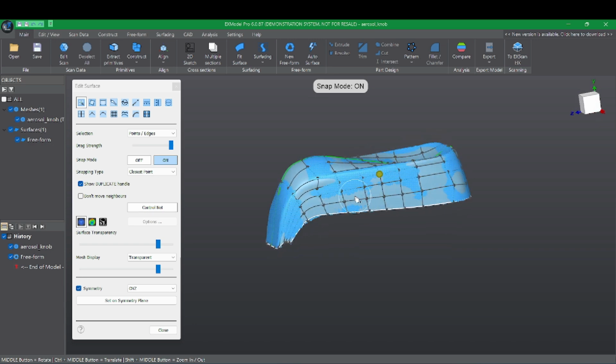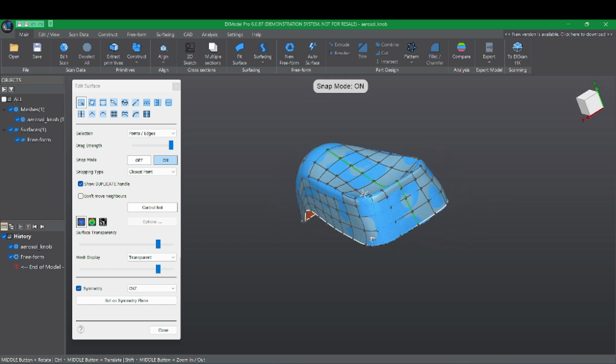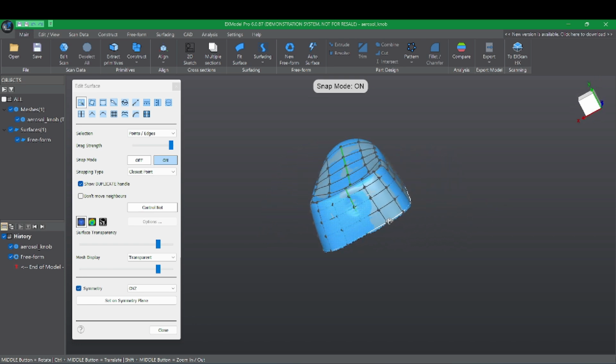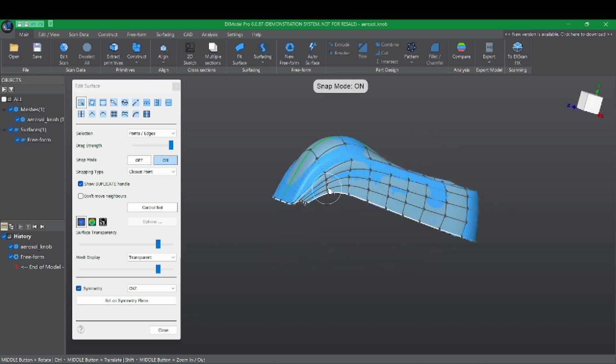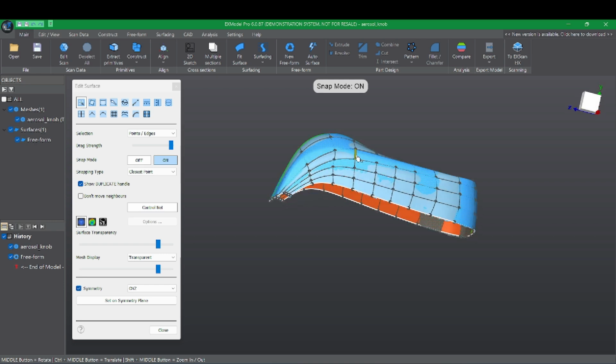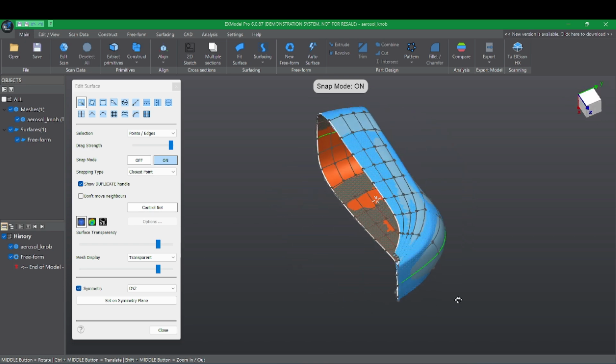One command which is not available in the context menu is what we call the brush tool. Holding Ctrl and Shift will enable the brush smooth. While you hold the Shift and Ctrl, you can use the mouse wheel. As you see, it changes the shape. Then when you hold the left mouse button, it actually starts smoothing the points around, while still keeping them projected on the surface. In this case, this is not good enough for me, so I can start playing with this, and in such a way we can just smooth our results.